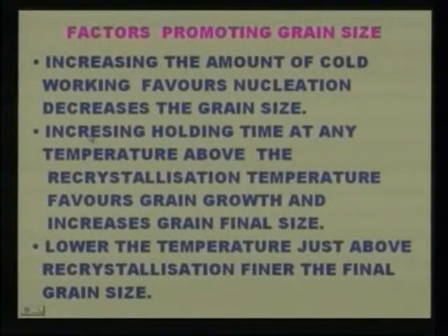Now see another factor, increasing holding time at any temperature above the recrystallization temperature, which favors grain growth and increases final grain size. Now see another factor, the lower the temperature just above recrystallization, the finer the final grain size.